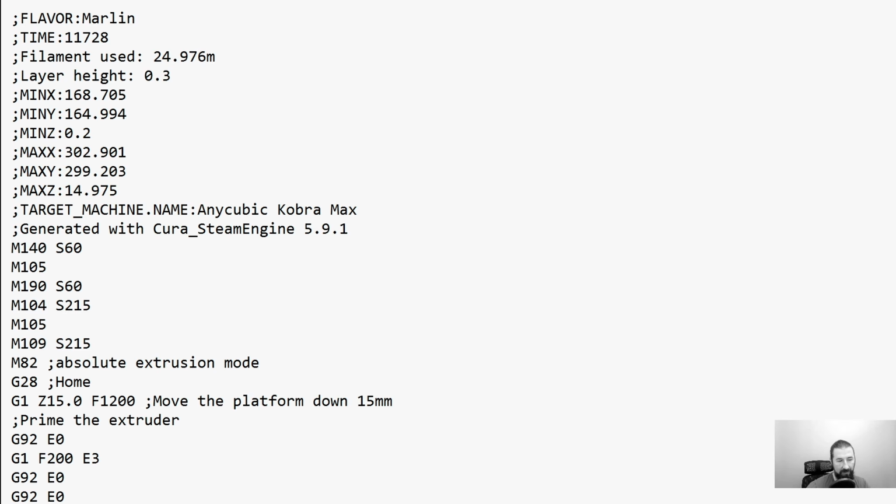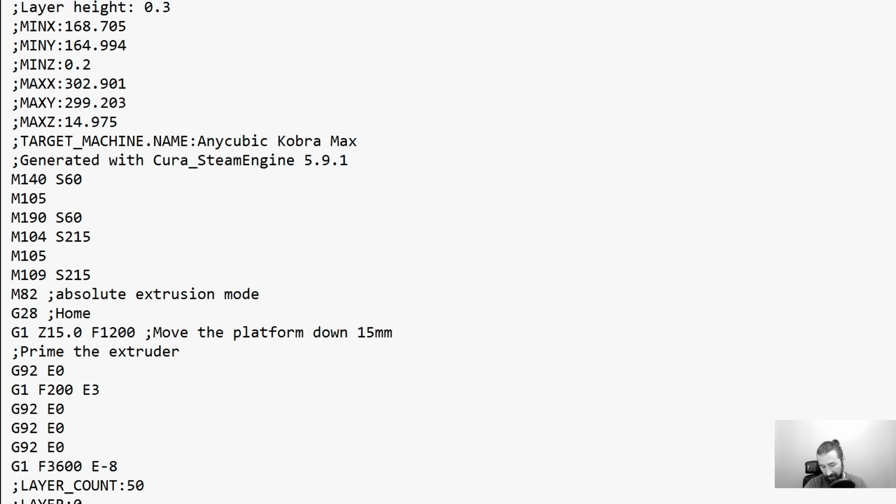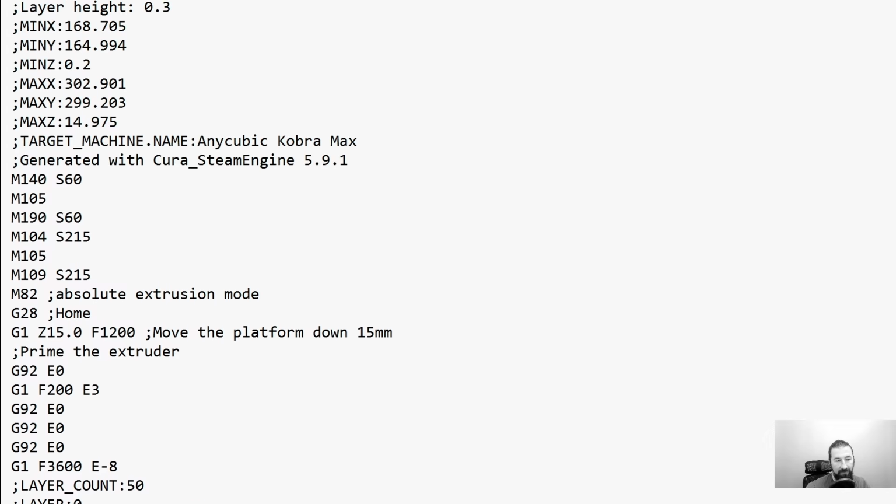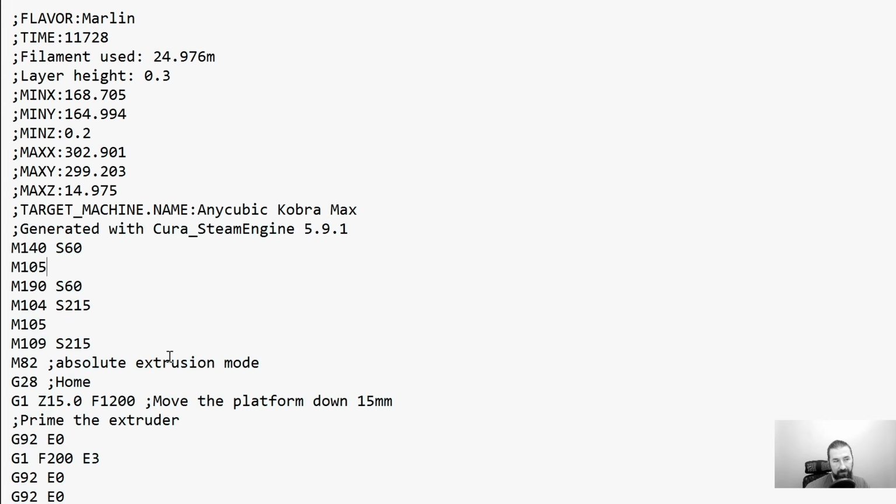So we put here some lines and some comments, because after these lines begins the normal toolpath itself. This is your geometry, which will actually be printed. And what happens before that? Those are pre-commands: some setup of the bed temperature, the extruder temperature, etc. These are standard commands, absolutely identical among all the different flavors. Sometimes you encounter different commands which are special for that flavor, but you need them once in these pre and post commands usually, and then you can just replace them.